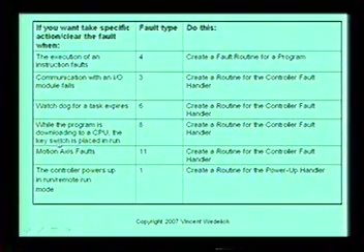While the program is downloading to a CPU, the key switch is placed in run. That's a fault type 8. I guess this could happen. I usually tell everybody to step away. Keeps me from having these problems.